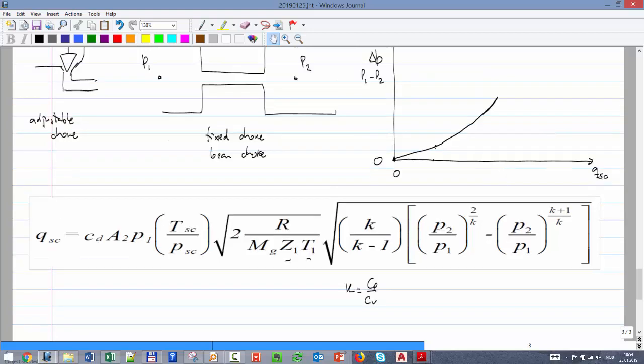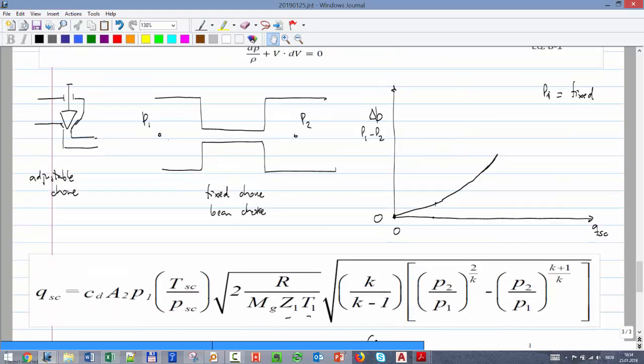So that means it's taking into account how this equation is derived. I go from point 1 to a point at the throat. And due to that contraction effect, the fluid doesn't follow exactly the path of the throat, but actually follows a smaller area. So that CD is multiplying the area at the throat, such that it matches exactly that.